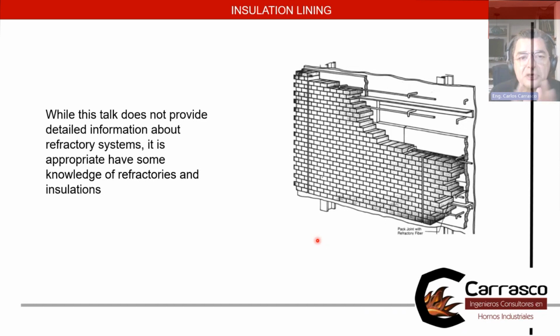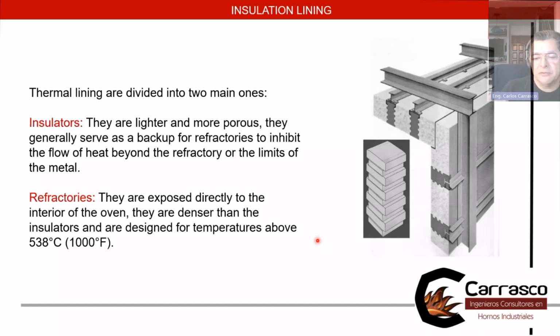Of course, there are many options that the vendors, the suppliers, the people who design this can let you know, what you need for a particular application. If you are using, let's say, aluminum melting furnaces, you need high alumina, like 90%, 99% of alumina into the bricks that can stand the aggressiveness of the aluminum in the process. The way you install the furnace is also a completely different technique.